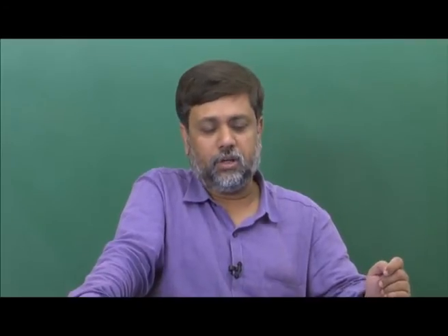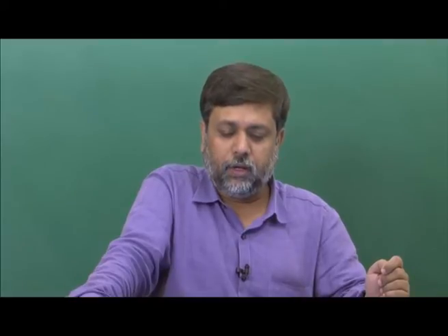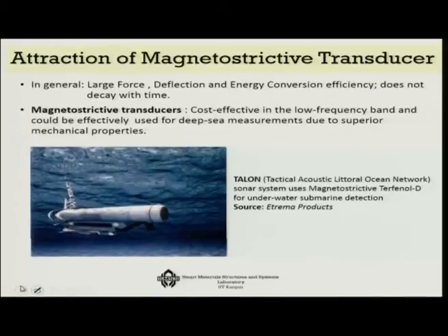Much unlike the piezoelectric materials where the discharge happens very fast, it does not get discharged very fast. So a magnetostrictive transducer will be cost effective in the low frequency band and could be effectively used for deep sea measurements due to the superior mechanical properties.